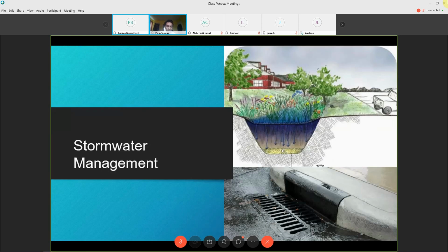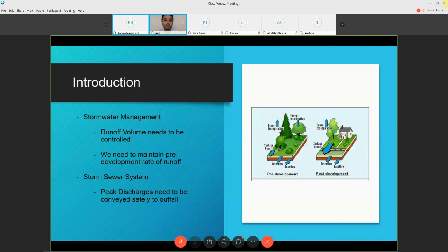So good evening, everyone. My name is Nabil Elkadiri, and I will be presenting the stormwater management aspect. Next slide, please. What we have to know is that stormwater management's main goal is that the runoff volume needs to be controlled. We need to maintain a pre-development rate of runoff, and through that develop 2 main alternatives that will allow us to do so.